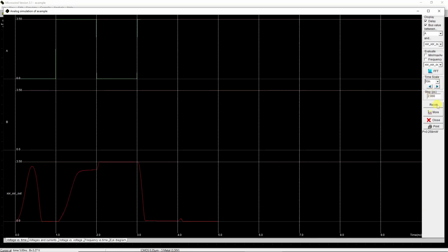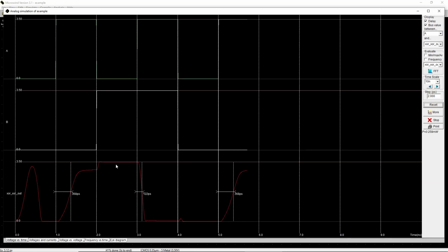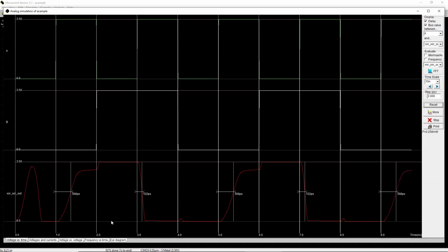Observe that the output swing ranges from 0 to VDD. For some logic inputs, the voltage swing is less than VDD. This indicates that due to area optimization, voltage swing for some logic inputs has reduced from VDD.